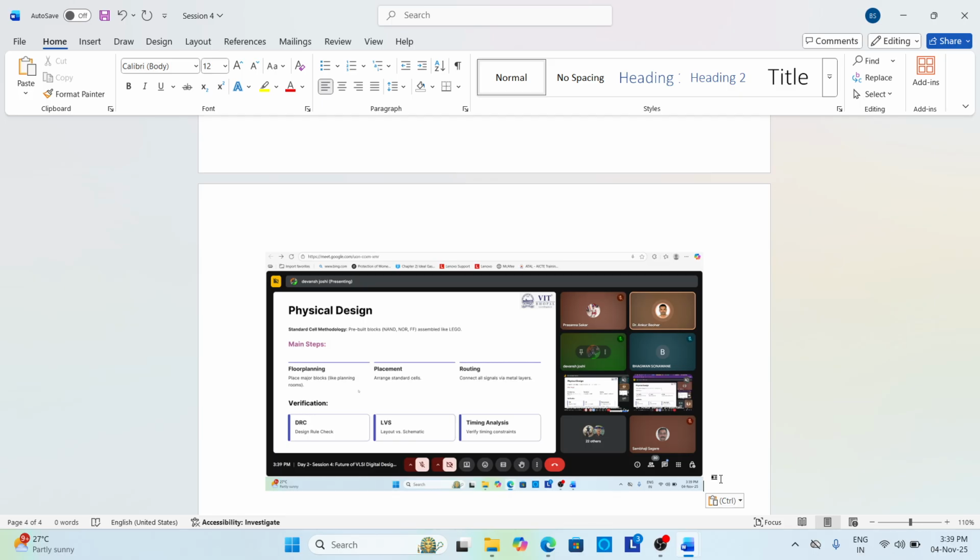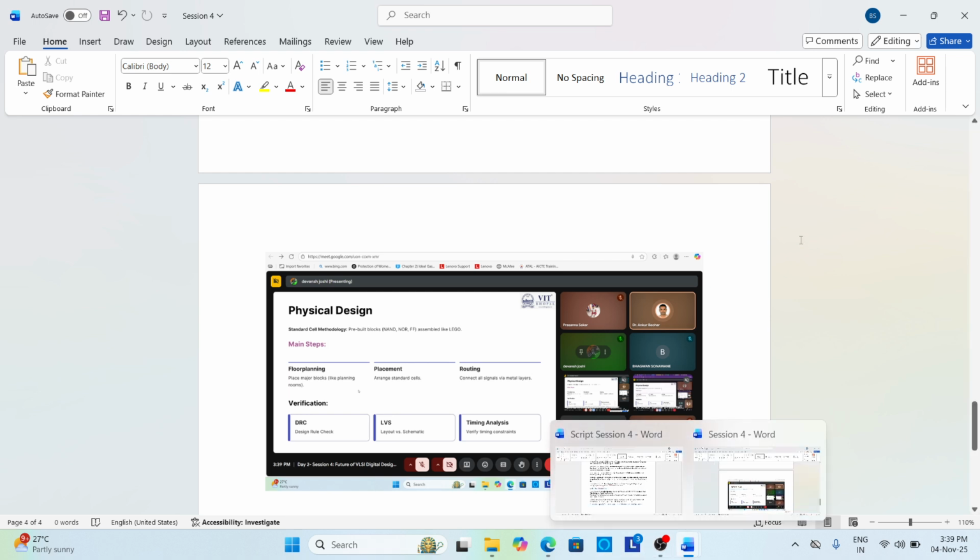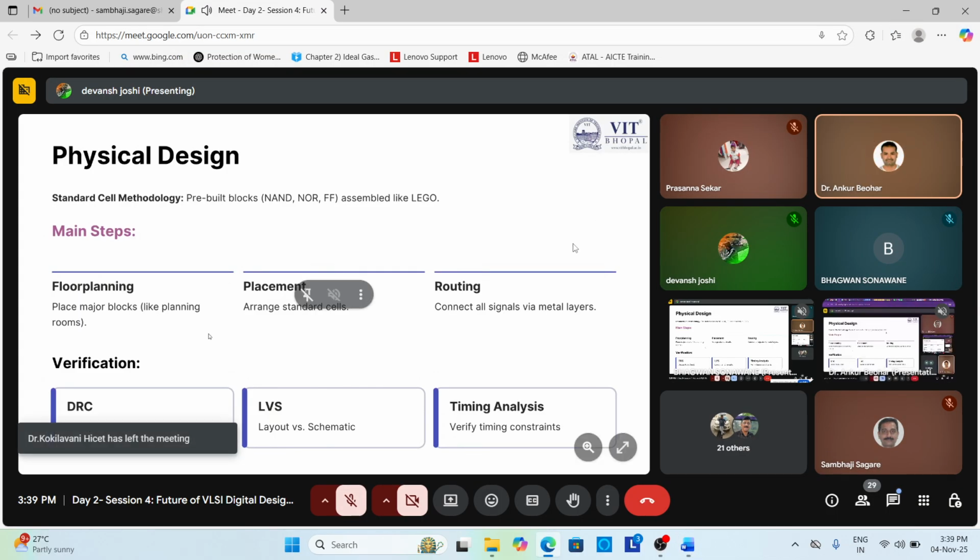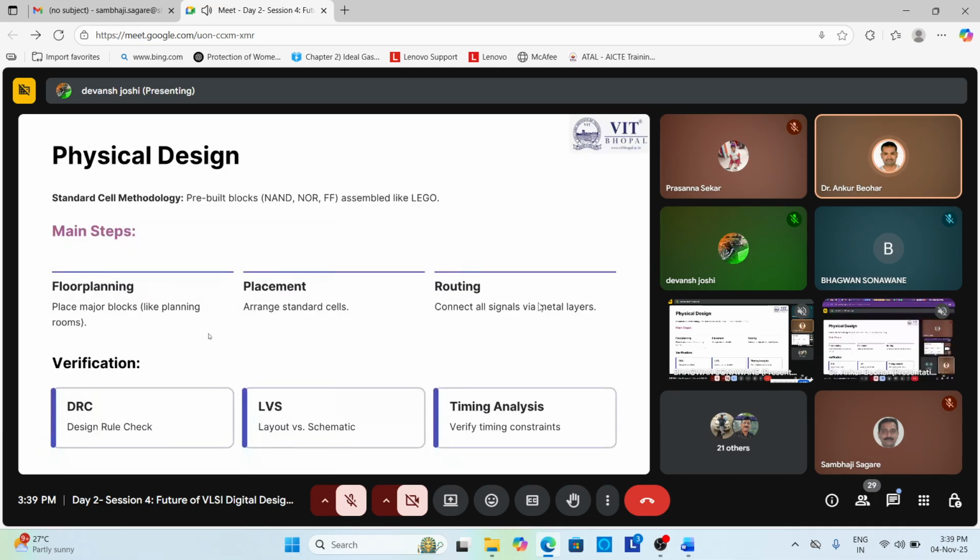Right now we can say core and die area placement, macro placement, pin placement, power planning. Similarly, if we go towards the placement, it is how the standard cells get placed inside the core boundary. It depends on how the placement is done and has a large runtime to perform the steps. These include the important steps in which the EDA tools perform to complete that placement.